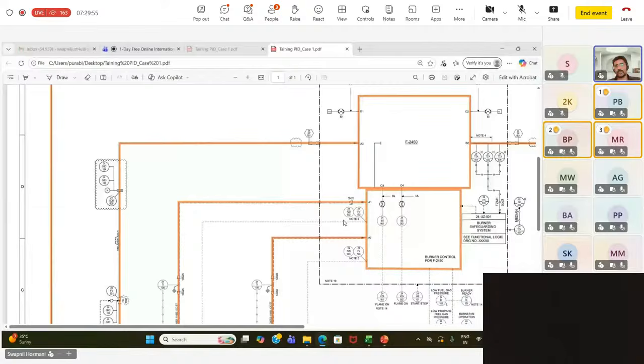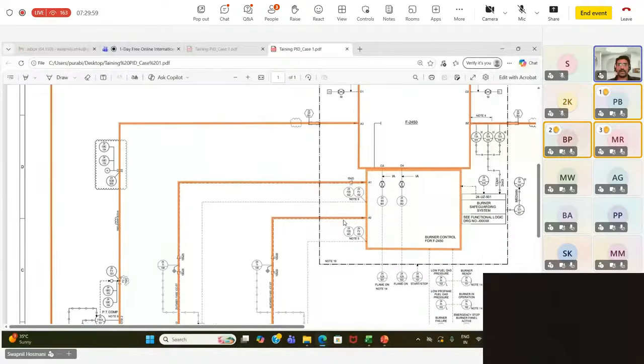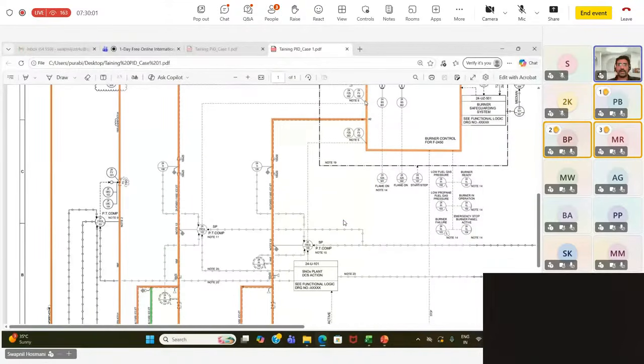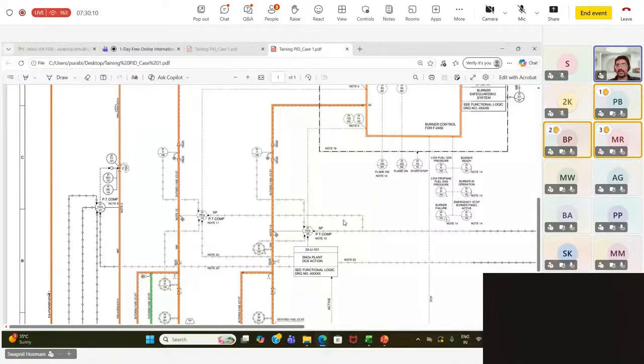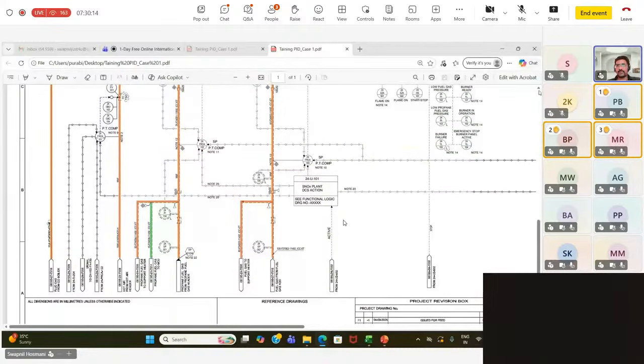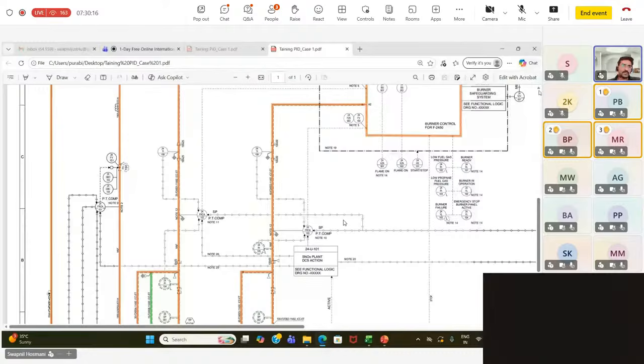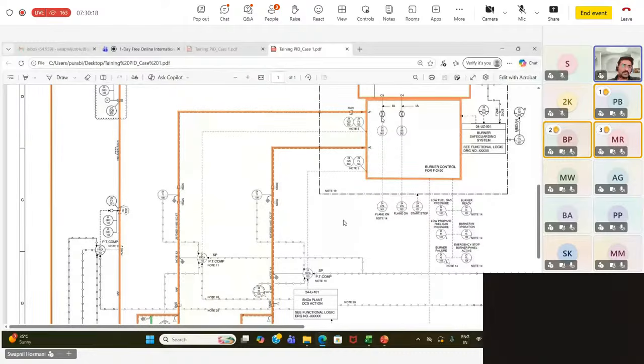But these two control valves are there. One of them is on the propane line, FV102, and the second one, 103, is on the fuel gas line, fuel gas to startup heater. So now we are contemplating a scenario where FV103 is partially closed, or less flow of fuel gas.